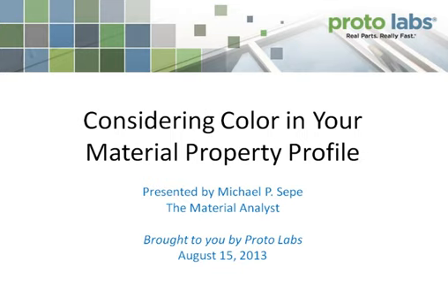And the fact that once color is added, the property profile does change. And it changes in sometimes surprising ways, depending upon the type of color that's being added, the polymer it's being added to, and how much color is needed in order to achieve a certain profile. But the primary thing that people are mostly concerned about when they start adding color is how does the part look? What are the aesthetics? Does the color match? Does it have the right hue? Does it have the right gloss, the right brightness? And very low consideration is given often to what is actually happening to the property profile of the material while all these aesthetic considerations are being given attention to.